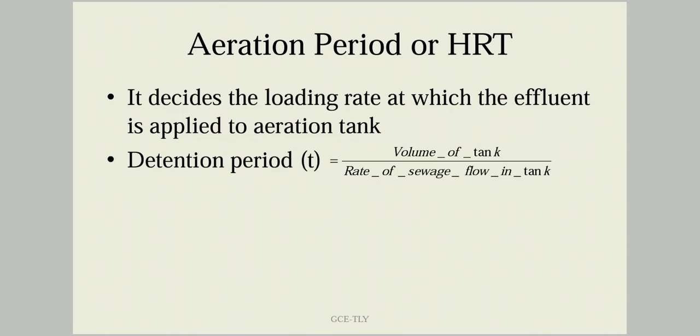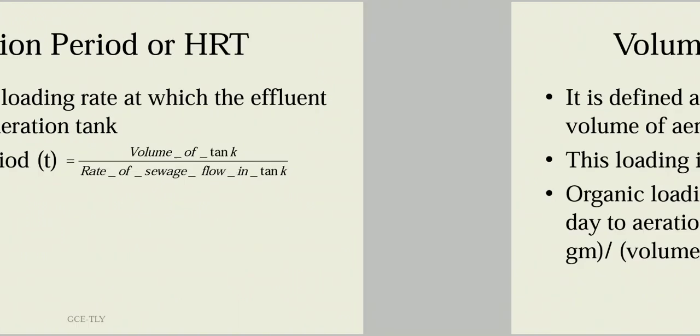So aeration period decides the loading rate at which the effluent is applied to the aeration tank. The rate of application of effluent to the aeration tank is called the aeration period, and it is also called the detention period or hydraulic retention time. It is the ratio of the volume of the tank to the rate of sewage flow in the tank, that is V by Q, which gives you the retention period.